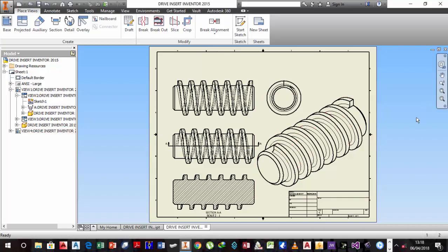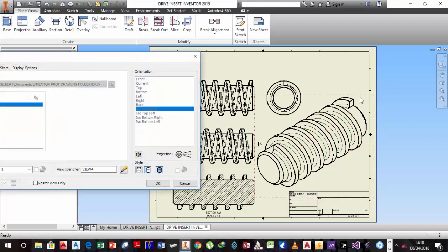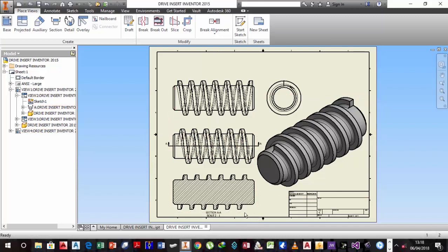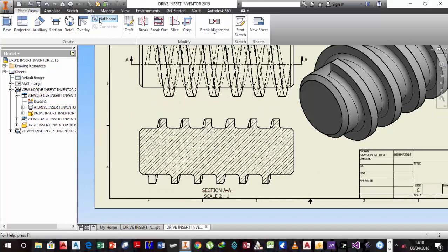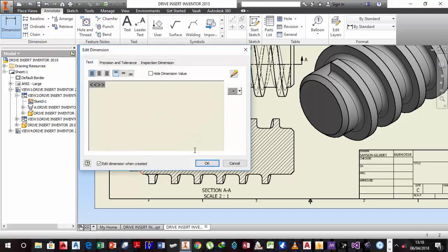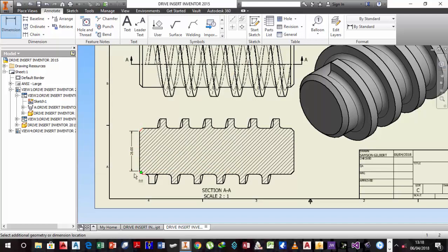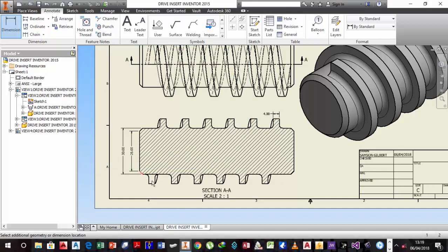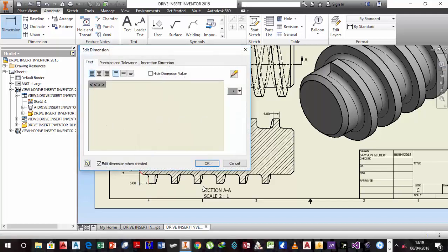If you want to leave it this way, or you can double click on it, then ensure that it is realistic. Press OK and it changes. Alright, then let's quickly dimension our drawing from the section we've just gotten. Go to annotation, click on dimension, get to your point, you drag out 26, do the same thing, say OK, do the same here, drag out 30, OK, let's get our width, get point, this point is 4, beautiful, say OK, let's click on this point, and this point is 6, say OK.